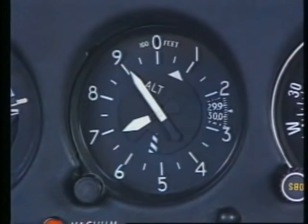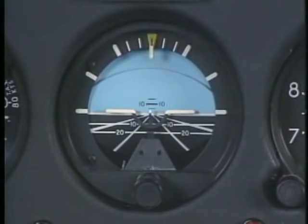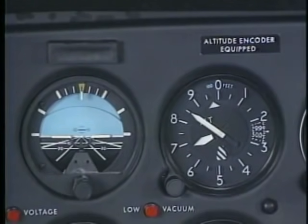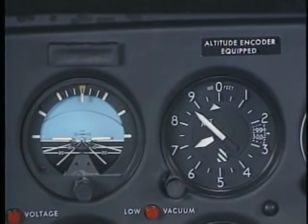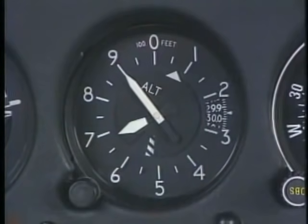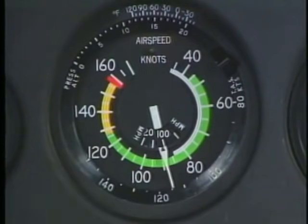Normally, if the altitude deviation is less than 100 feet, use a correction of a half bar width. If the deviation is greater than 100 feet, initially use a full bar width. Once the new pitch attitude is established, check the altimeter, vertical speed indicator, and the airspeed indicator to see that you have made the proper correction.